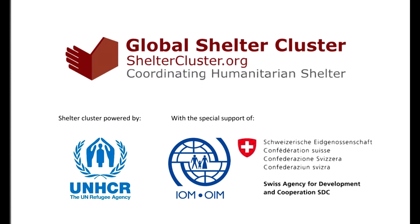Here, I would like to draw your attention to a very important issue. The first thing, the thickness of the compacting layer depends on the strength of the soil, the CBR of the soil that we are working with, and these tests or equivalents are available at the Idlib University and also at Alba'ath University. I think it's the North university.